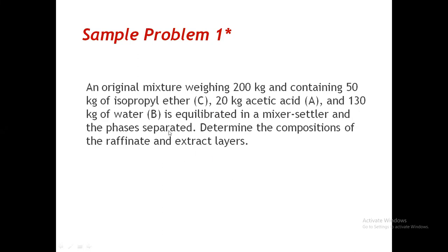So your isopropyl ether is supposed to take out the acetic acid from the mixture, separating it from water. That way, water can be decontaminated of the acetic acid using the solvent isopropyl ether. So we want to know what would be the corresponding compositions of the raffinate and the extract layers for this particular problem. So the first thing that you're going to do in here is, of course, you should be able